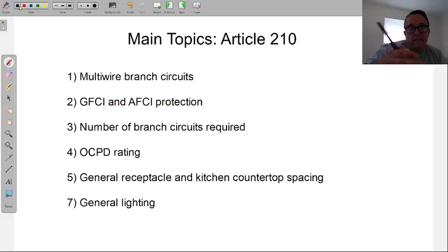We're going to get to, in this Article 210, this thing we call voltage drop, which is, I lose voltage the further away the thing that is being plugged into this circuit is. If it's 5 feet away, I don't lose any voltage. 120 starts at the breaker, 120 ends up at the outlet. But if that outlet is 300 feet away, 120 starts at the breaker, I might have 98 volts at the outlet. So we got to compensate for that.